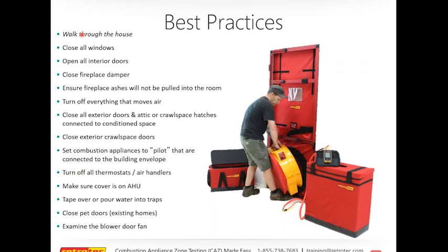This list of setup is pretty much the same house setup for a combustion safety test. So the first best practice that I want to recommend to all of you is that if you're doing a combustion safety test and you're doing a blower door test, it's probably a good idea just to set them up all at once.